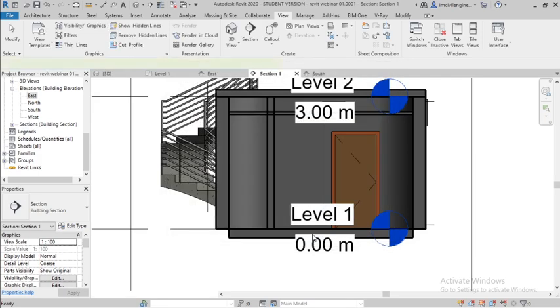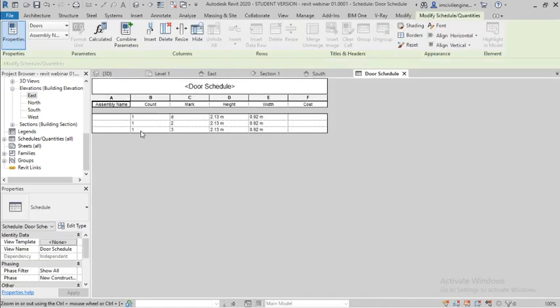If you click OK, you can see the beauty of Revit. It's automatically showing the quantity, door scheduling. You can see it's an assembly code. We have not mentioned the assembly code. Count, it's 111. Type mark D. Here, if I change it, it will be automatically updated.